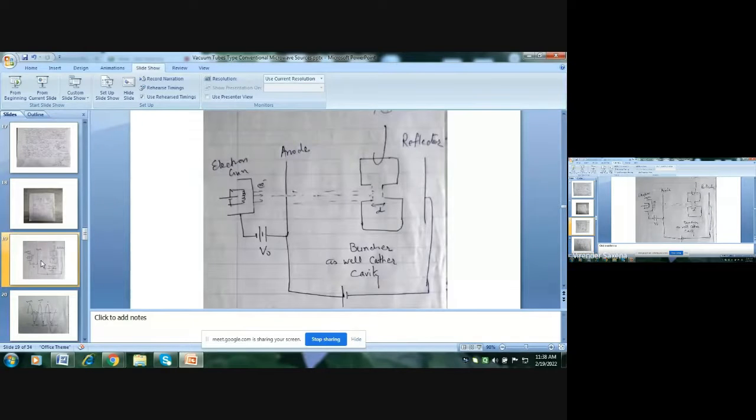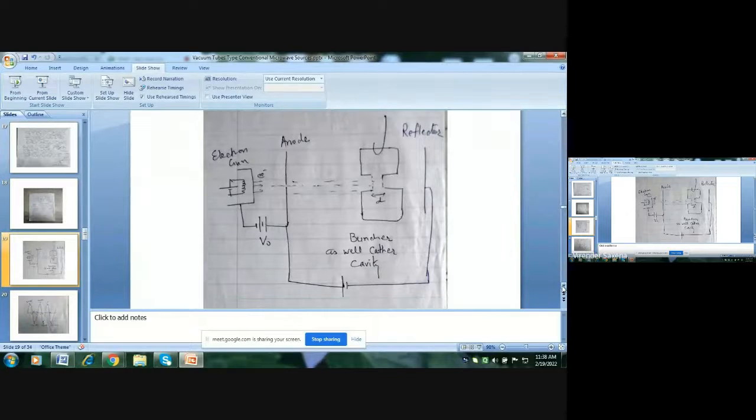That means after a 3/4 time period, or 1 plus 3/4 time period, at this instant, so that more electrons can transfer energy to the cavity, and this energy is extracted by a loop conductor to the waveguide. So in a reflex klystron,